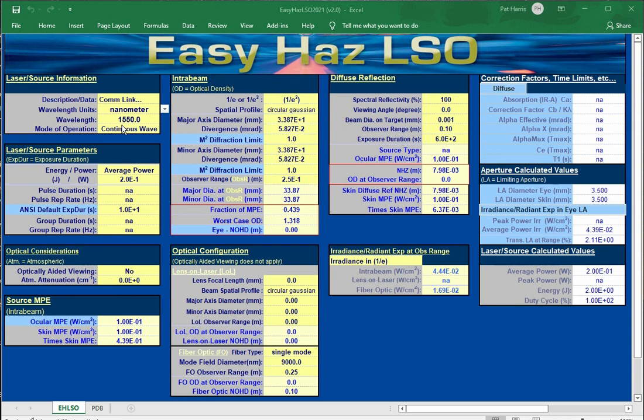I worked with a laser that was a YAG. We had an OPO on it, changed it to 1547. This was a Q-switched pulse, and you do the analysis on that laser and you find that for 1547 Q switching, it was by no means safe to look at all. So there is no such thing as an eye safe laser unless the output is below the MPE.